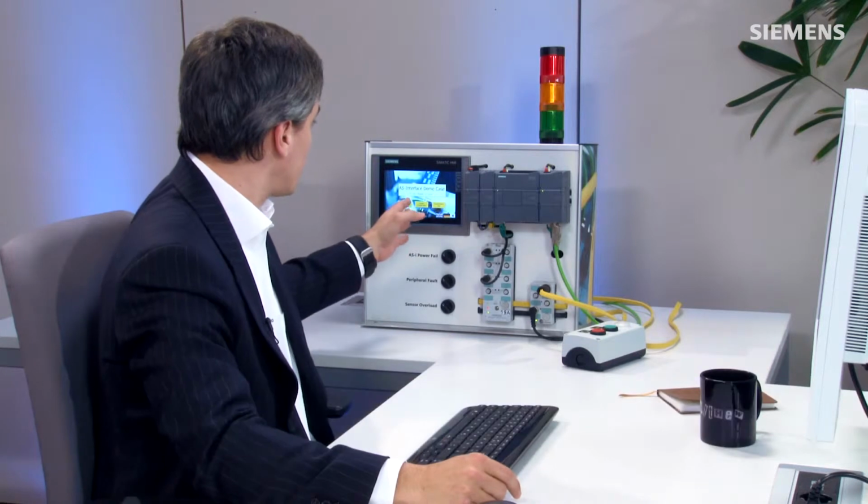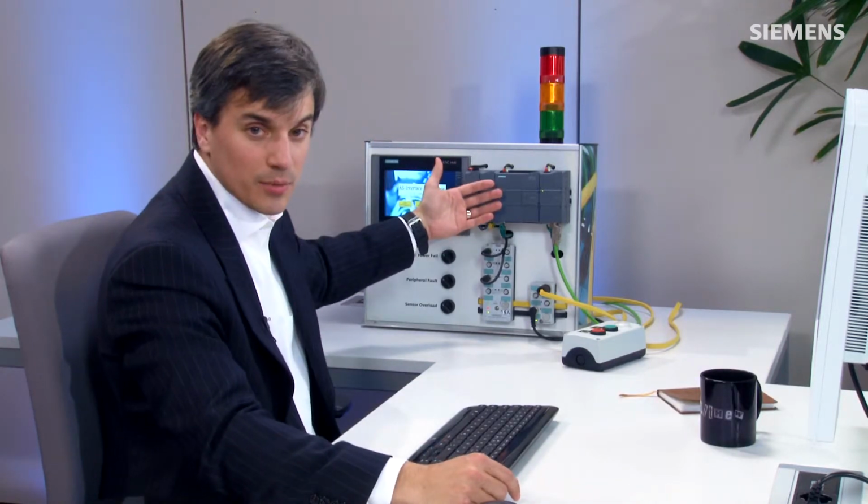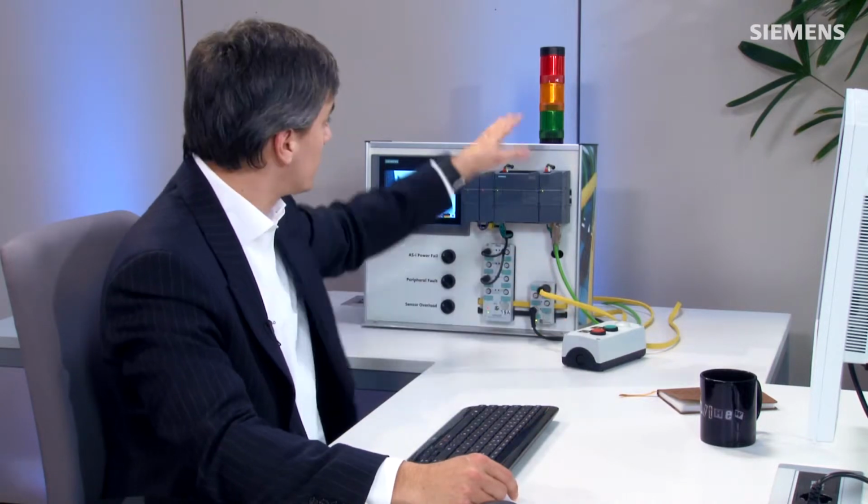The ability to easily add an AS-i network to your current machine design can be a huge benefit to any machine builder. Let me show you how easy it can be. As you can see, here's my current controller and HMI panel. This is what we want to add this AS-i network to. So here's the master, an I/O block, a start-stop station, as well as a signal column.